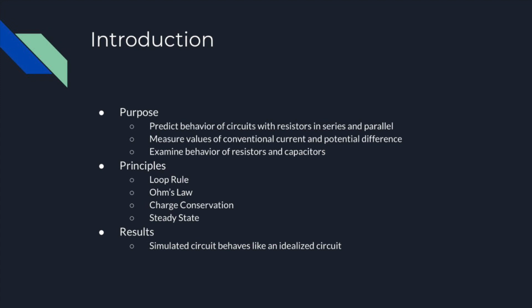With regards to my results, I found the actual values of current and voltage given by the model matched those predicted by the formulas, and that in an RC circuit, the magnitude of the current is time-dependent, based on an exponential equation.